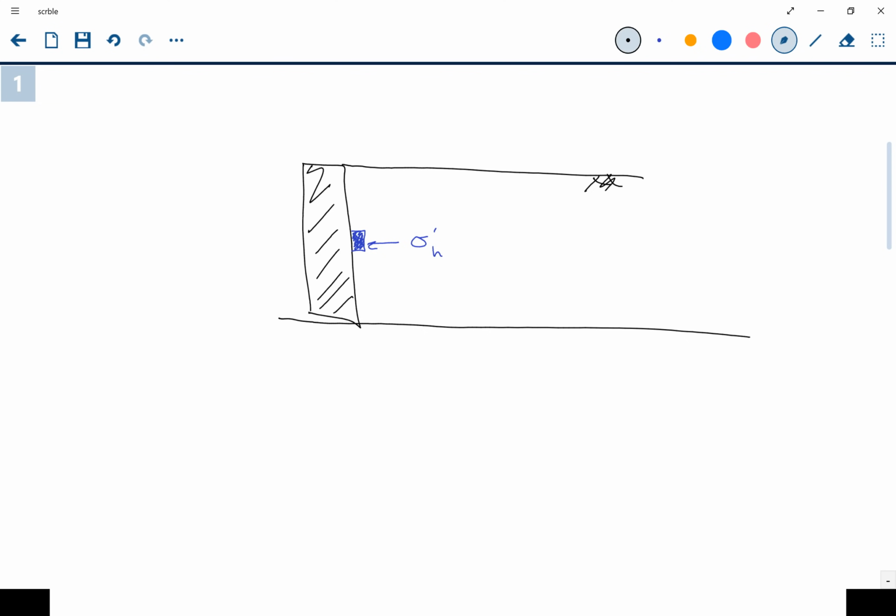Because we know that the horizontal earth pressure is simply equal to K times the vertical pressure, then K is simply the ratio of the horizontal stress to the vertical stress. So let's say then that because of this sensor right here, we can track what the earth pressure coefficient is as we slide our wall to the right into the soil or to the left away from the soil. So let's start by taking it away from the soil. So this would again be the active case. If I slide the wall away from the soil, it's going to cause a failure plane behind the wall to develop. There's going to be opposing forces along that failure plane. Everything will be an extension. So this is going to be the active case.